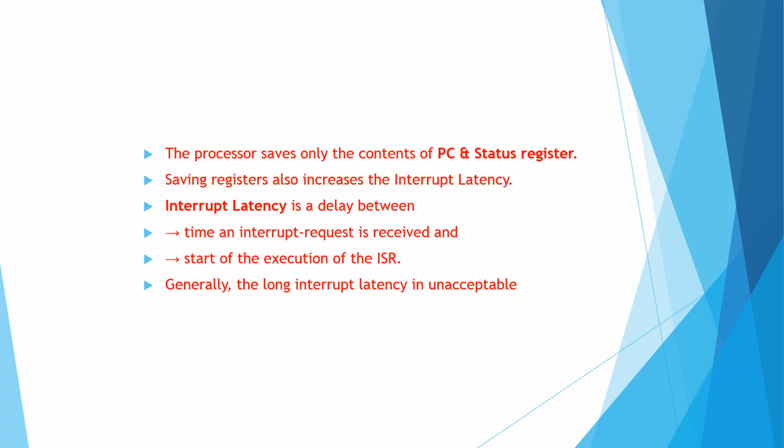So the latency means the delay between the actual interrupt request and the actual service. That is the delay between when an interrupt request is received and the start of the execution of the ISR. Generally, a long interrupt latency is unacceptable because whenever the IO device requests an interrupt, the processor needs to provide the service immediately. That means it needs to send an acknowledgement, that is the INTA signal, to the IO devices.